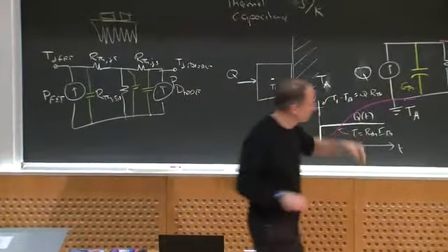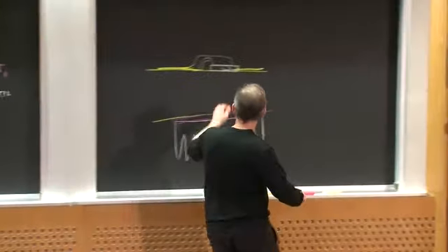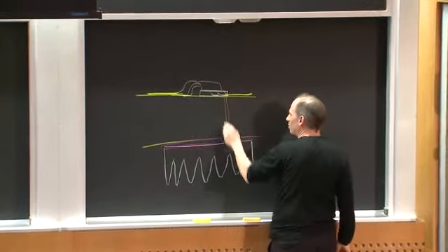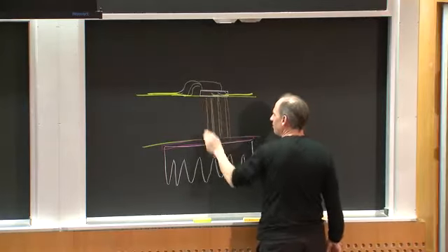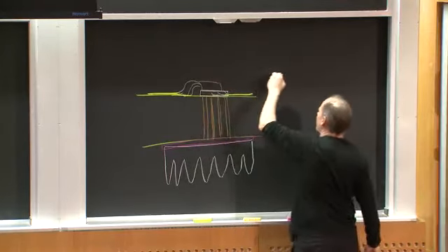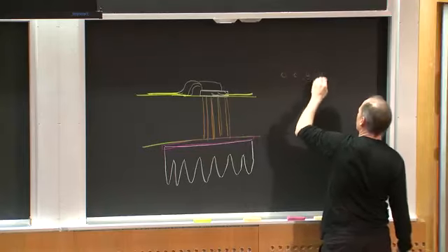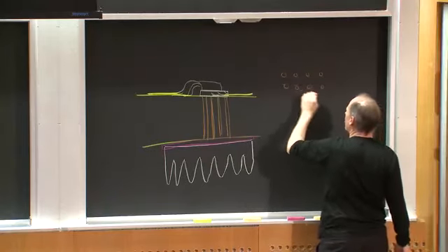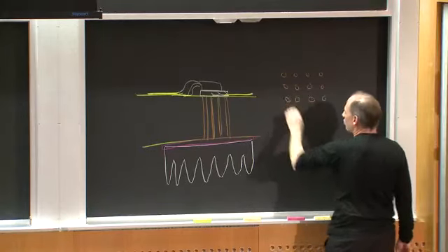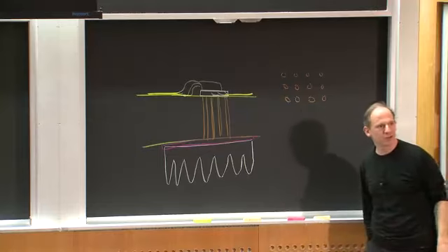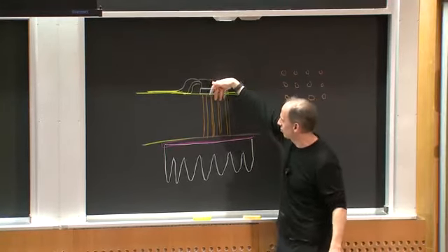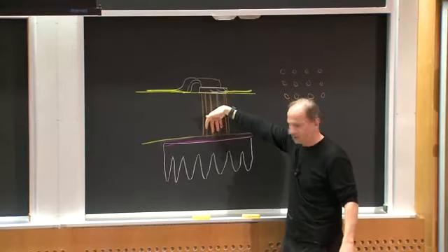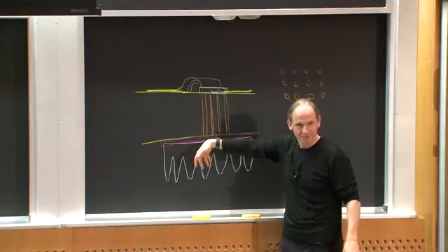So one of the things you will often do is put thermal vias in the board. If I looked at this from the side, you'll drill a bunch of holes through the board, and you'll put what's known as a via farm. If I looked straight down on top of it, you'd see a bunch of holes drilled in the board like this. Why? Because those holes will then be plated with copper, which is a good thermal conductor, and it'll help me transfer heat down through the board to the interface material to the heatsink.